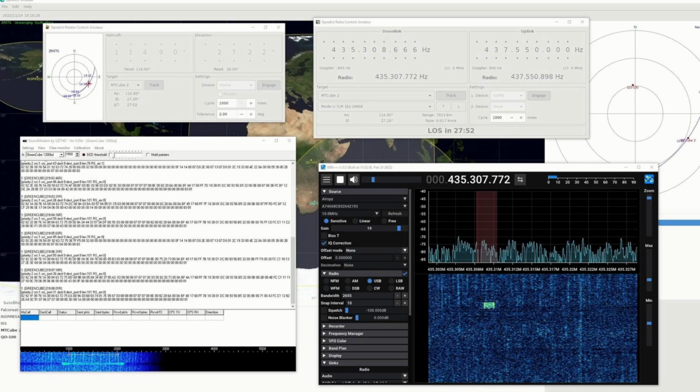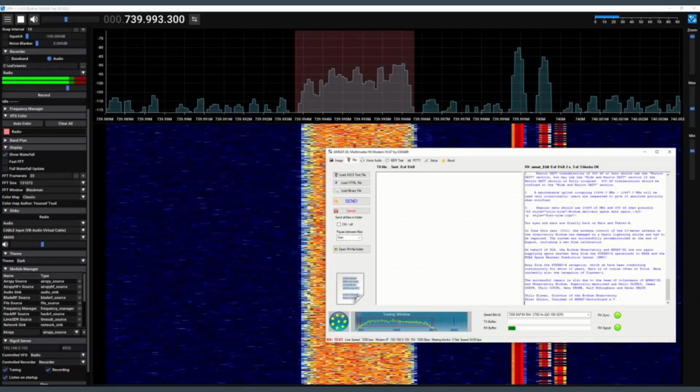This is usually done by piping the audio received from the signal on your SDR into a separate application that performs digital signal processing. If that sounds too complicated, then you can start even simpler by using software to demodulate the signal into its binary data, and then you develop an application to decode the binary data. What the binary data presents usually depends a lot on what kind of information the satellite is transmitting.